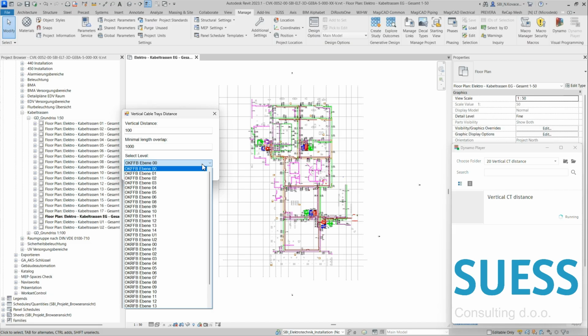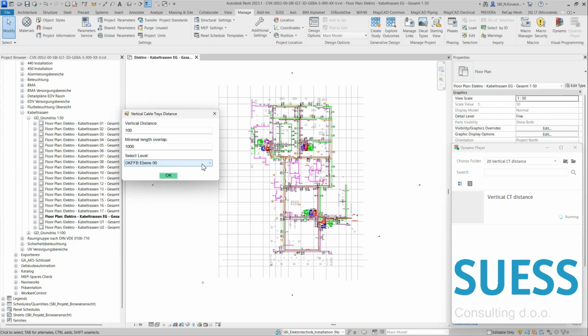So if you're running a calculation of each and every cable tray versus the other, if you don't have some geometric scope inside the script, that will be very painful in terms of calculating all those combinations. So the quickest and easiest way for us to handle that problem is that you will need to choose from which floor we will collect all cable trays, and we will run the calculation on that domain.